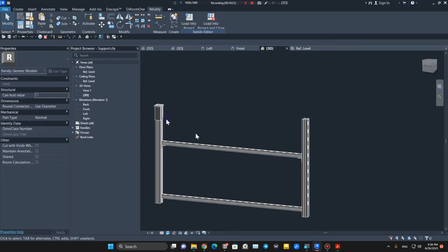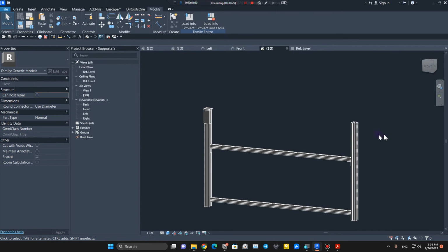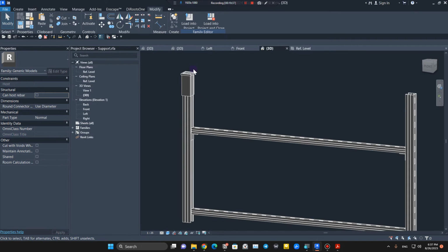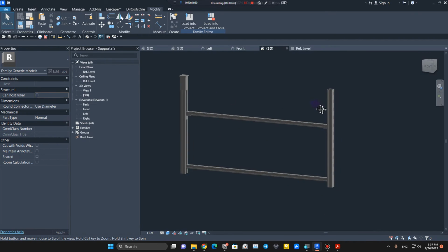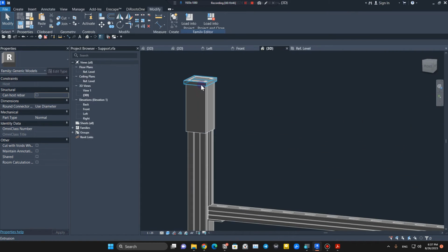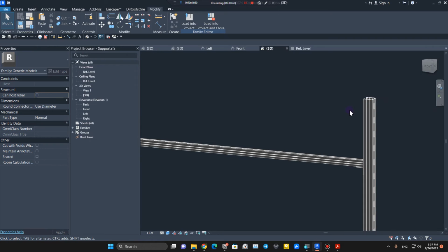Okay, that's great. And now we need to place them for here too, but there is a tip to do that, because the first point of the line-based families is in the same place. There is no problem for the first part, but for the second part, because it is different in each family, you have to lock these two families to the right place to make sure that they will stay in the right place that they are.